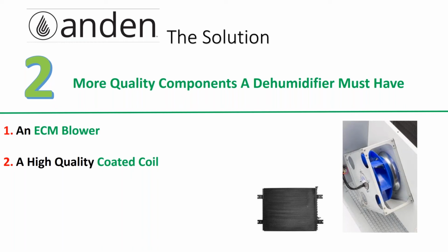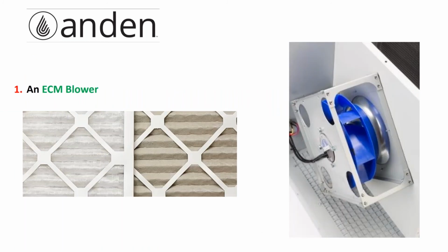Two quality components a dehumidifier has got to have to survive your room. They got to have an ECM blower and they got to have a high quality coated coil. But that ECM blower is beyond important. It is crucial to making a dehumidifier work. See, dehumidifiers are only as good as the amount of air moving through them. If you're not passing air through, that dehumidifier can't remove water from that air.